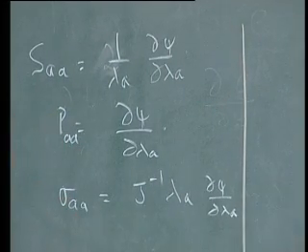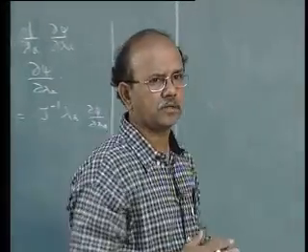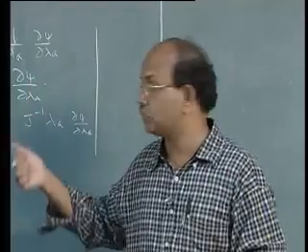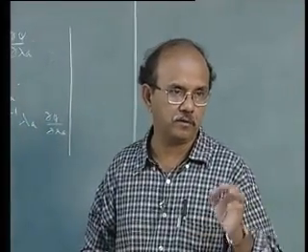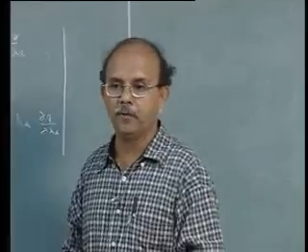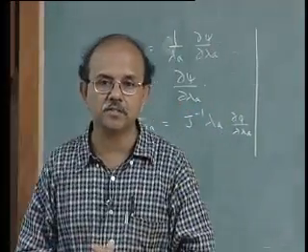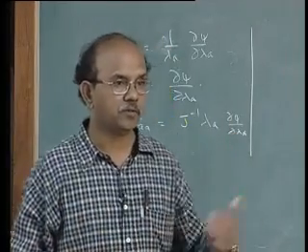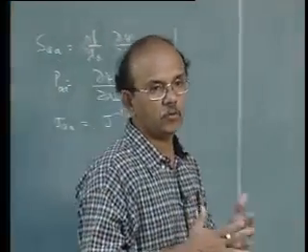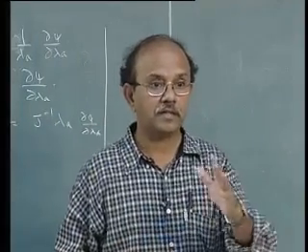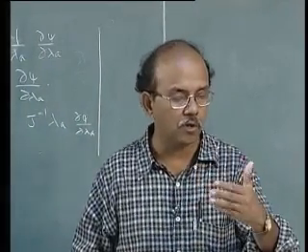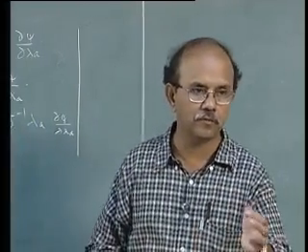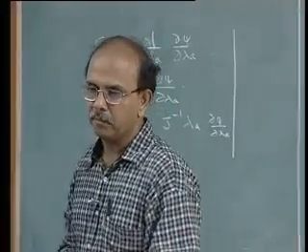Diagonal terms. It is very common today to work, most of the numerical analysts work with stretch-based constitutive equations. That's the reason why I had put this down. It becomes much simpler to implement it using finite element analysis, instead of looking at the constitutive equation as we did before this in terms of just I1, I2 and I3. Not that that's wrong, but it's easier to work when we look at this kind of thing. We'll come back to this in a minute.